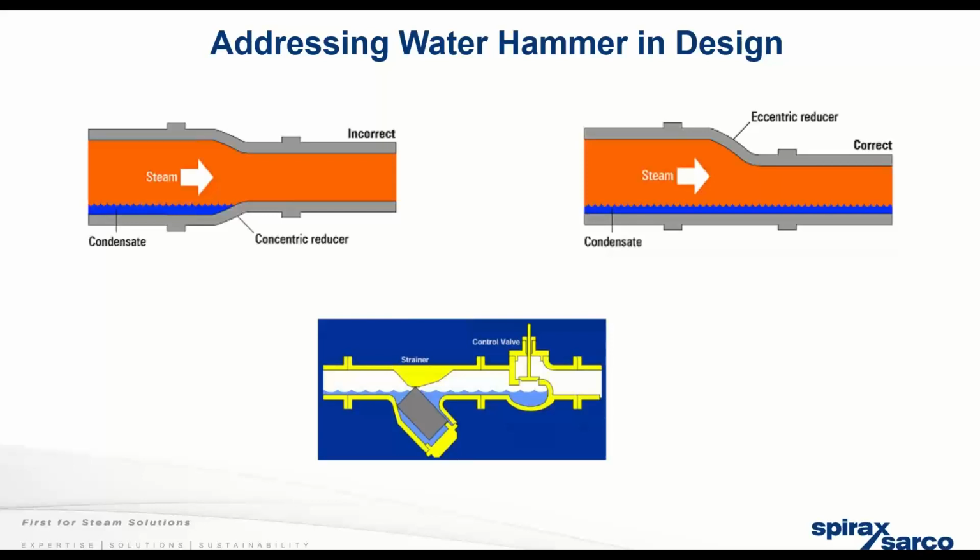The next picture is of a strainer, and it's a little bit of a pet peeve of mine. If you look carefully at that strainer, a couple things come to mind. In a steam delivery system, we put our water strainers or our fancy strainers in line, and then we put the yoke down, and then we fill the yoke with water. It creates a number of problems, but the big one is we've got a puddle of water there, or a huge volume of water. And two, we create a pinch point for the steam, which creates a very high velocity region and may impact the performance of our heat exchangers, et cetera.